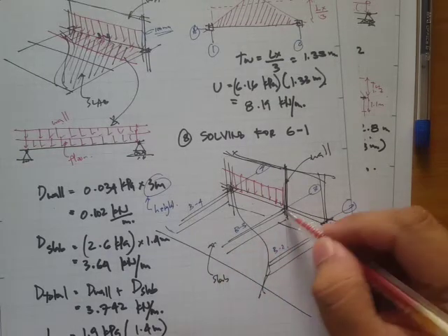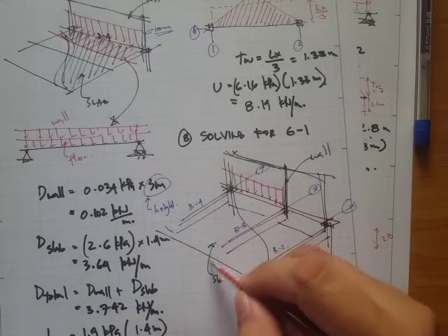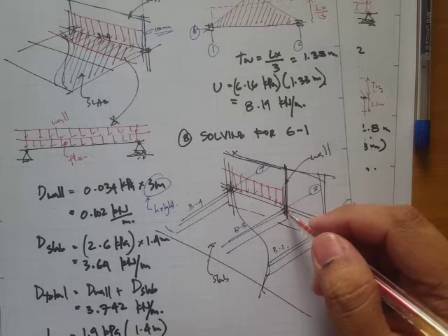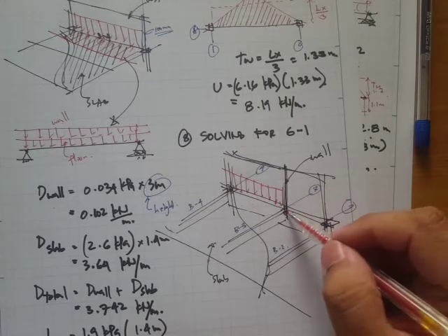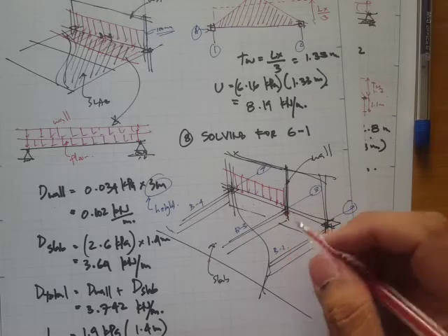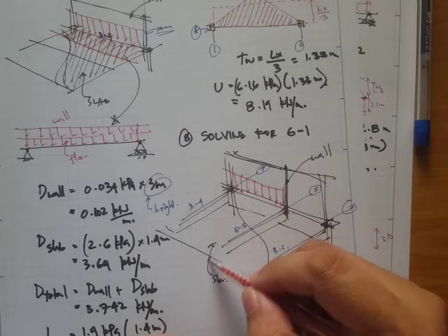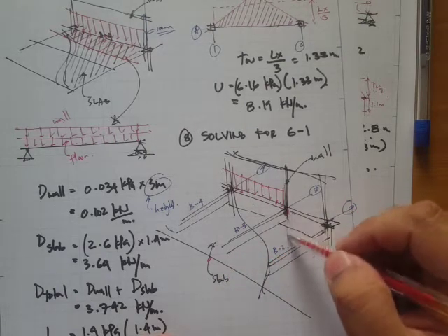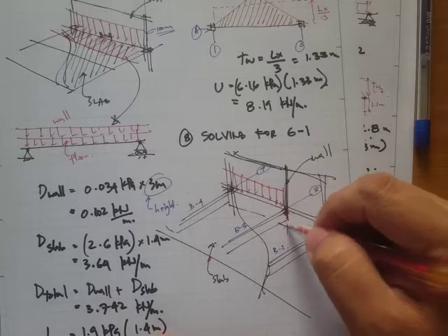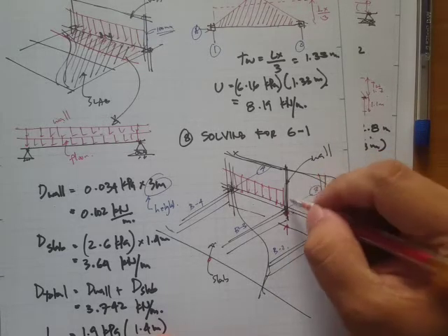If you recall what I said earlier, these are supports. So these are joints, or something like the boundary conditions of this beam B-3. You can model this, for example, as a simply supported pin-roller support, or you can also model it as fixed conditions. So these reactions right here, this joint or support reactions, will induce a point load on this girder.